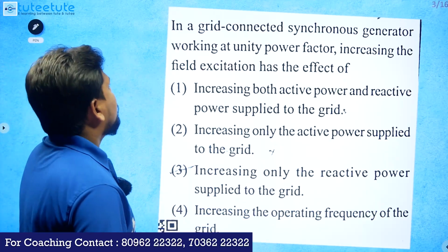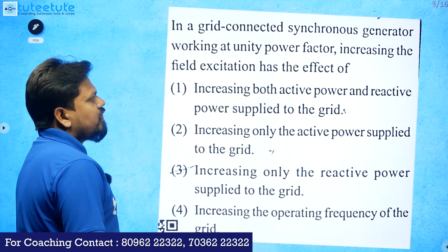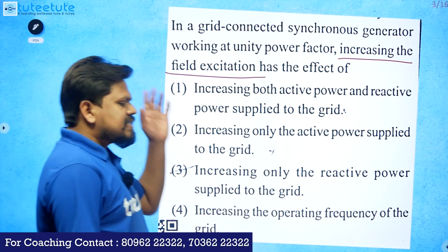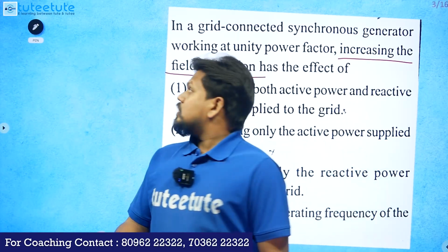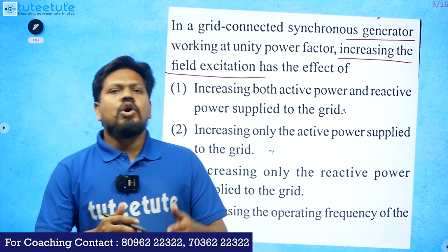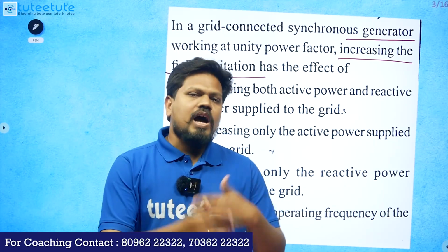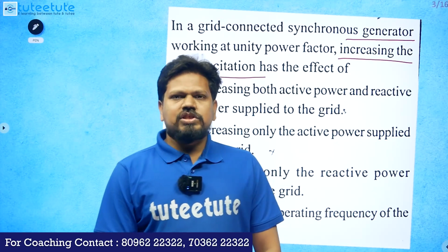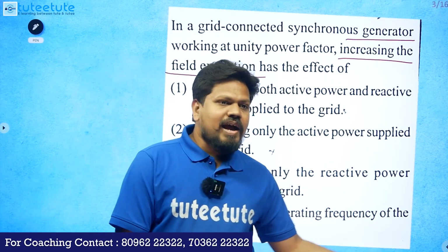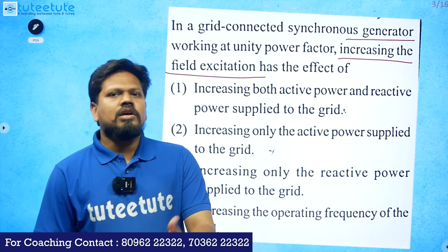Next question. In a grid connected synchronous generator working at unity power factor, what is the effect of increasing the field excitation? This is a synchronous generator. Whenever you increase the field excitation, what will be changing? The flux, the operating flux in the synchronous generator, will change, but that doesn't change the active power. Active power changes whenever the mechanical input is increased. Whenever excitation changes, only the reactive power changes.